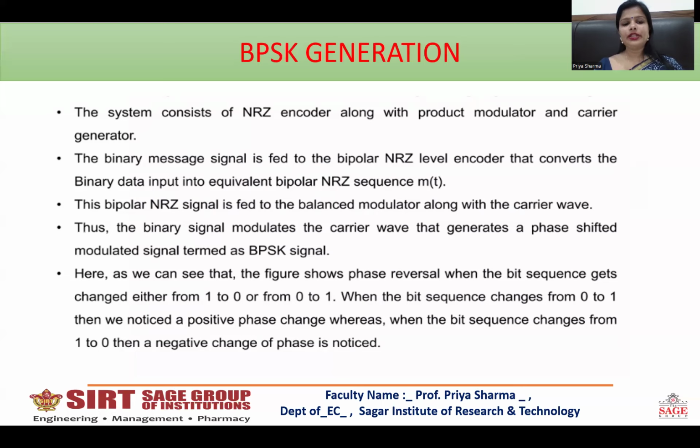This bipolar NRZ signal is fed to the balanced modulator along with the carrier wave. Thus, the binary signal modulates the carrier wave and generates a phase shifted modulated signal termed as the binary phase shift keying signal. Here, we can see a phase reversal when the bit sequence changes from 1 to 0 or 0 to 1. When the bit sequence changes from 0 to 1, we notice a positive phase change, whereas when it changes from 1 to 0, a negative change of phase is noticed.